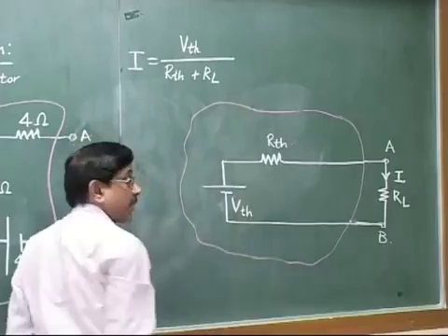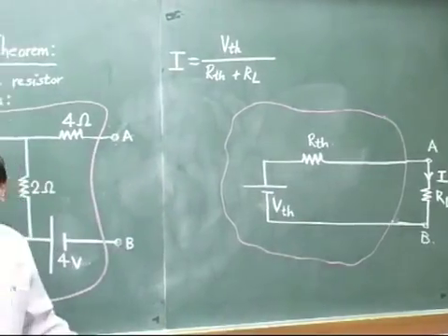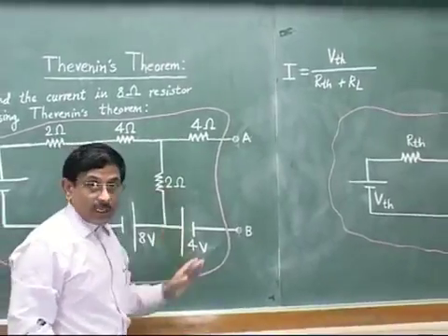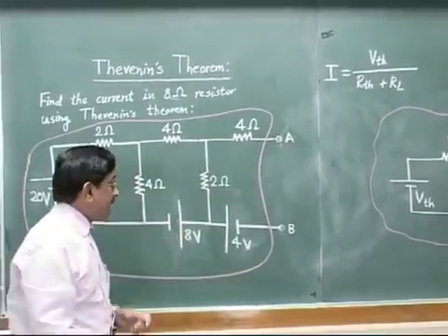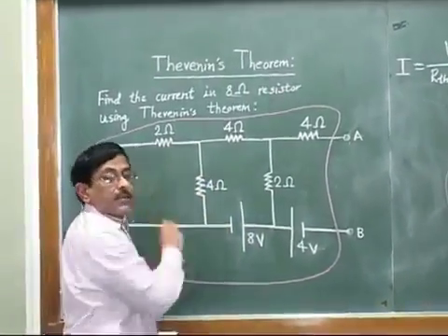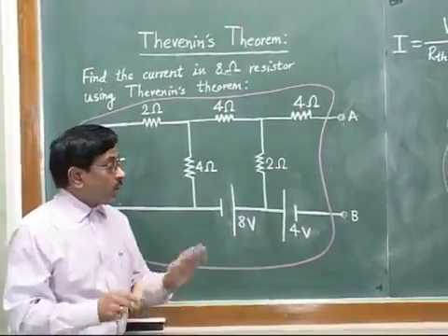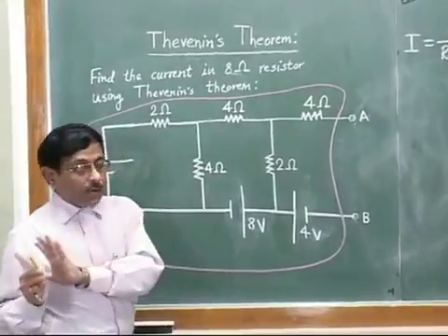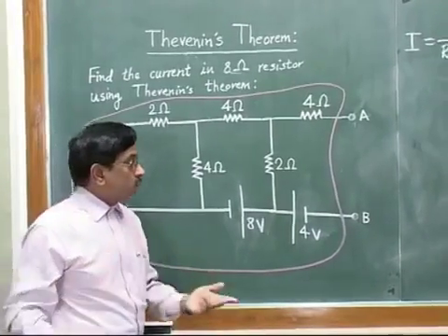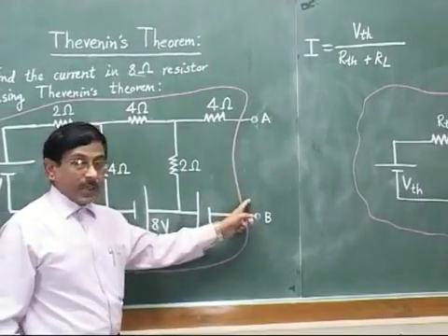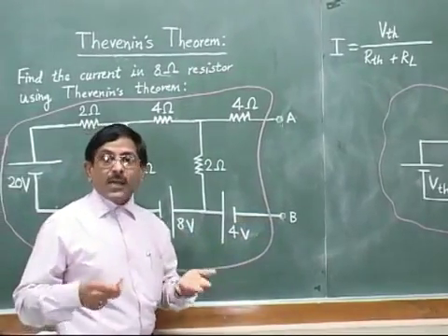So this is the simplest idea that Thevenin has suggested for finding out the current in the given load resistor. Okay, so simple central idea. Such a given circuit, we want to find out current in any given specific resistance. We remove the resistance, call it a load resistance. Once we remove it, we get the two open terminals. Then across open terminals, we perform certain operations.